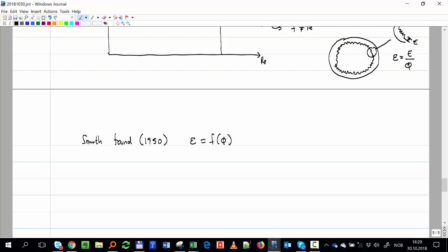If I have a small tubing, I have a certain roughness, and if I have a big tubing, I have a certain roughness. So he proposed that for gas, the friction factor will be just a function of diameter, and it will be 0.0077 divided by the diameter to the 0.224.